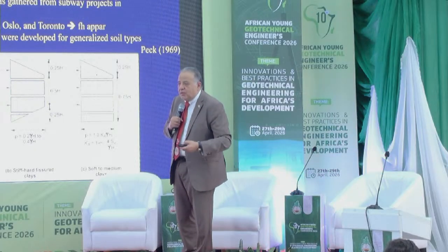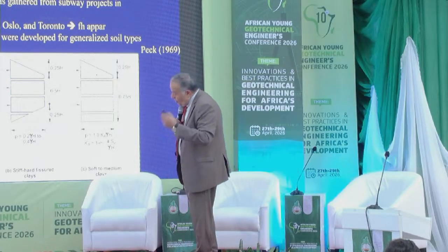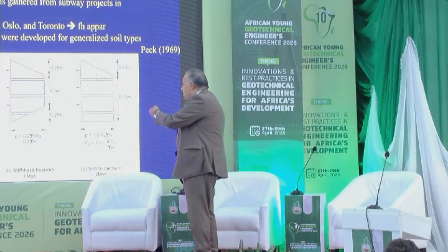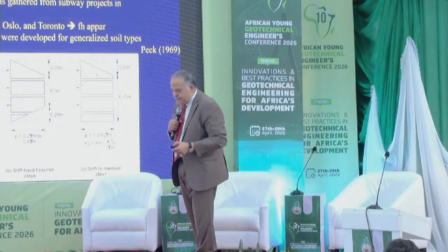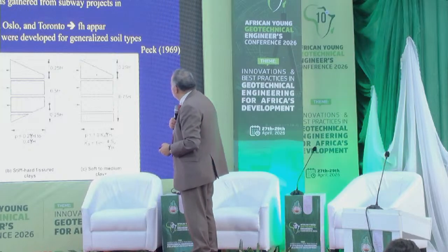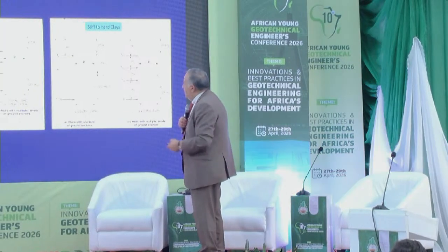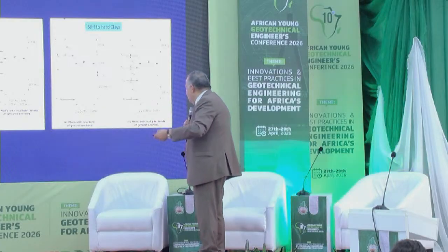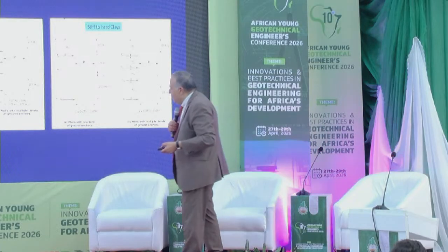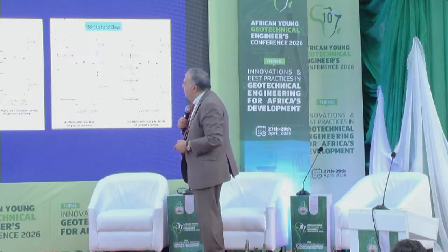They monitored the forces, not the pressures, and they got these envelopes that are used in the profession. Further development after that, FHWA, again, this is for sand, for stiff, hard clay, and so on. It's available.